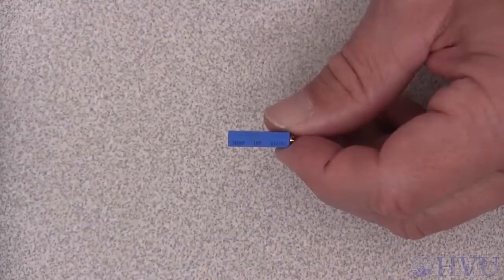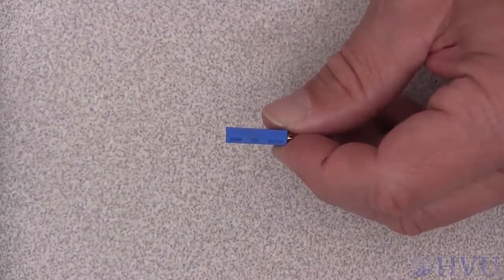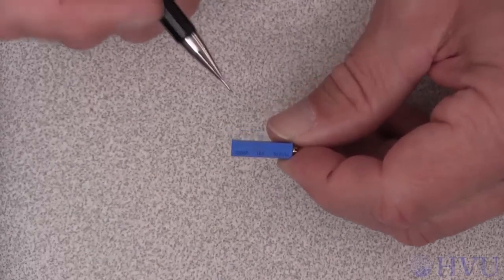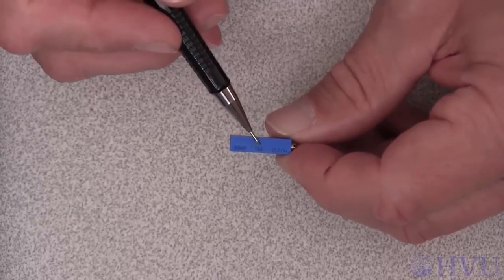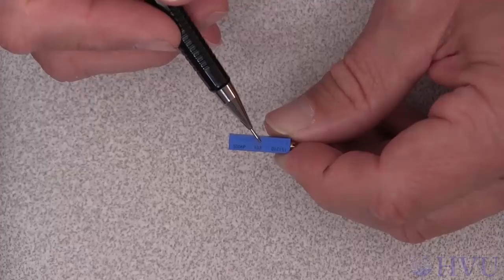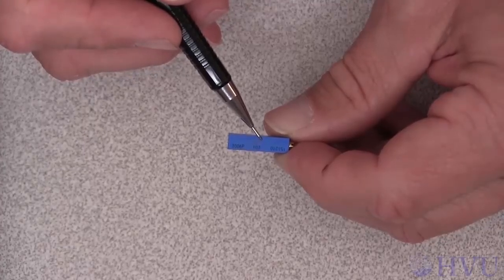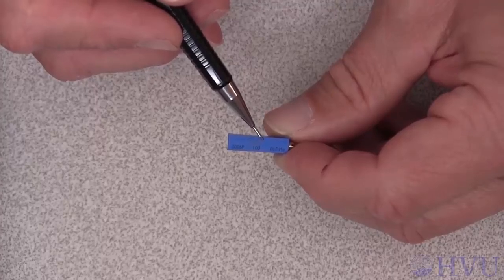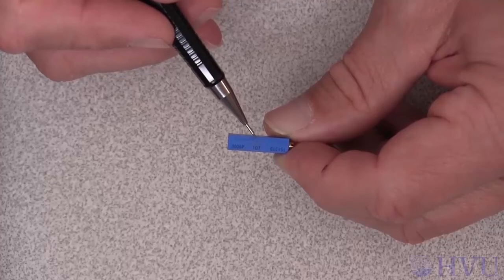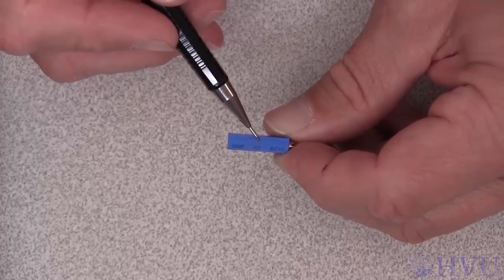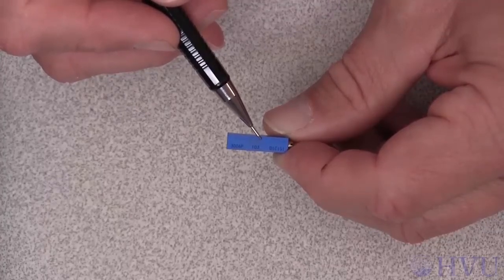Now let's use a DMM to set the resistance for a potentiometer. The maximum resistance for this device is encoded on the side of the pot as 3 numbers. The first 2 numbers create a 2-digit number. This 2-digit number is multiplied by 10 raised to some power indicated by the third number. Our potentiometer is encoded as 103, so its maximum resistance is 10 times 10 to the third, or 10 kiloohms.